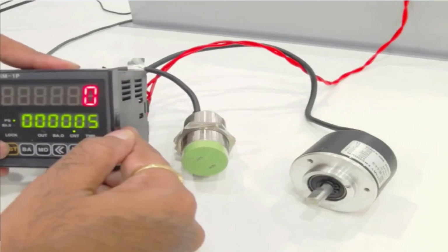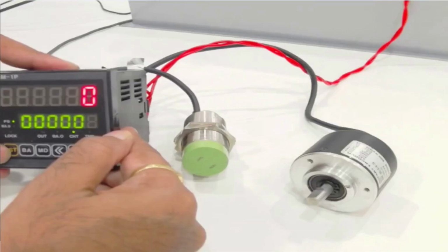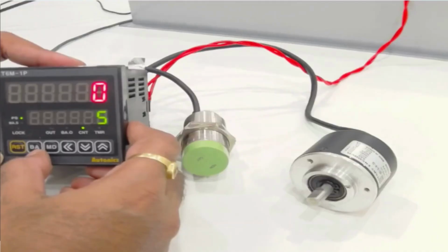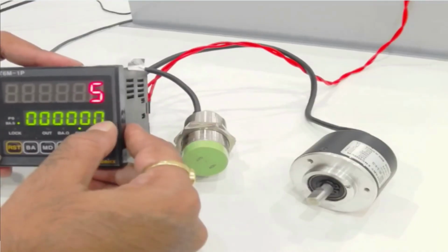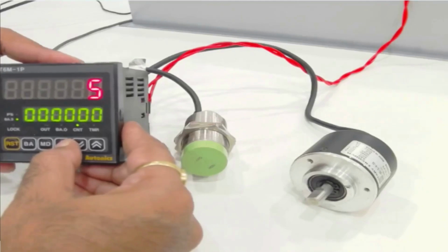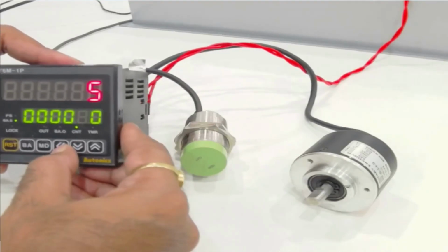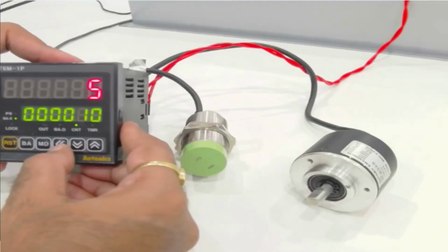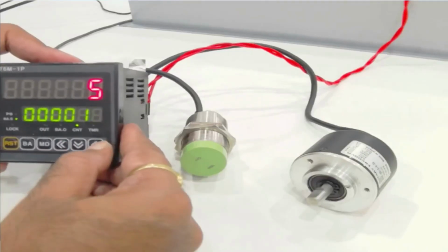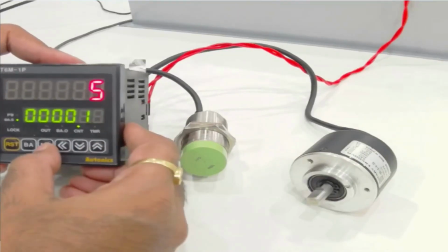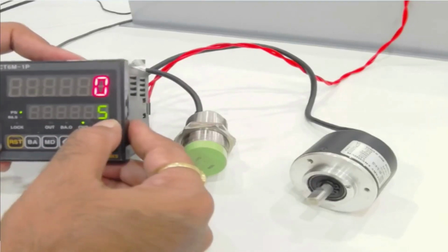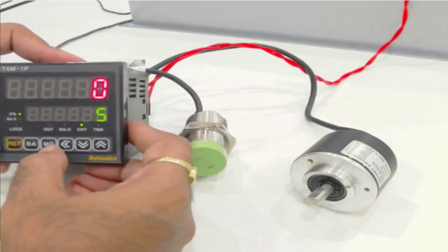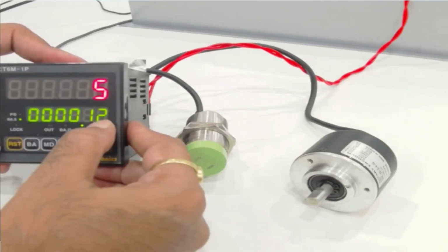So these are the number of jobs which will fall into the box. And also there is a batch set point required. So you can press the BA button and here you can enter the set point for the batch. Say 200 will be more to simulate over here, so I'll change this 200 to say 12 boxes as my set point right now. And I'll enter the MD key. So this is my preset value for the counter, number of jobs: 5 jobs need to be put into the box, and my batch set point is 12.